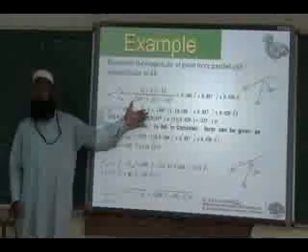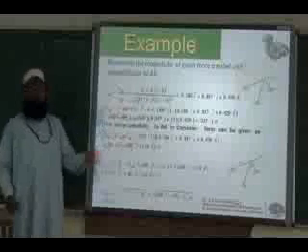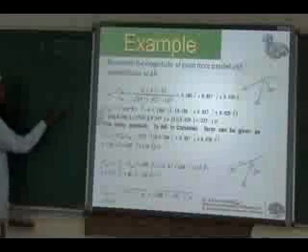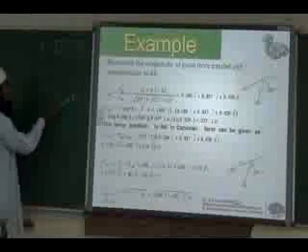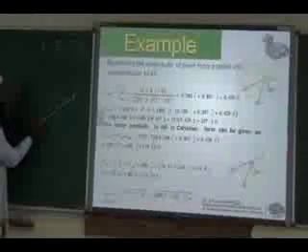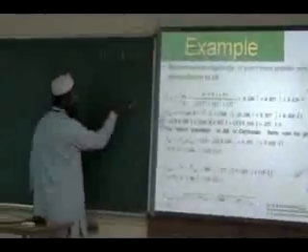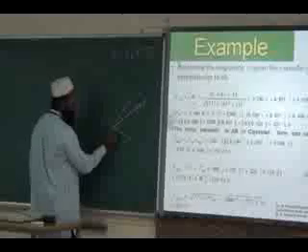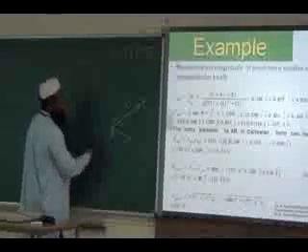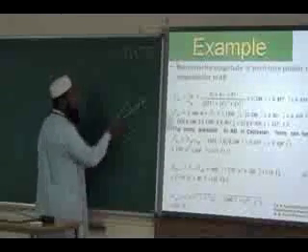For that we use the dot product concept. So this is the given force, 300 Newton. Okay. So we have to resolve it into two components. So this line is parallel to the cable AB. This is B, this is A. Parallel to it. So we have to resolve it into two components.